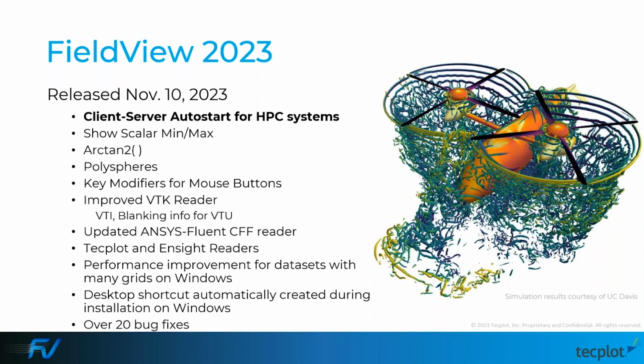So the speed ups, the additional performance, are going to add up. And for instance, it is really interesting to use parallel when you're doing things like creating a pretty long video where you have to go through a lot of time steps and compute complex surfaces for each time step. If you're doing such a process where CPU and file I/O are going to dominate over the rendering and outputting the image, parallel is going to speed up your operation and allow you to do things like getting the end video sooner, or maybe produce more videos in the same amount of time. But it's just that the speed ups that you get for one time step add up. There's no parallelization over time in FieldView.